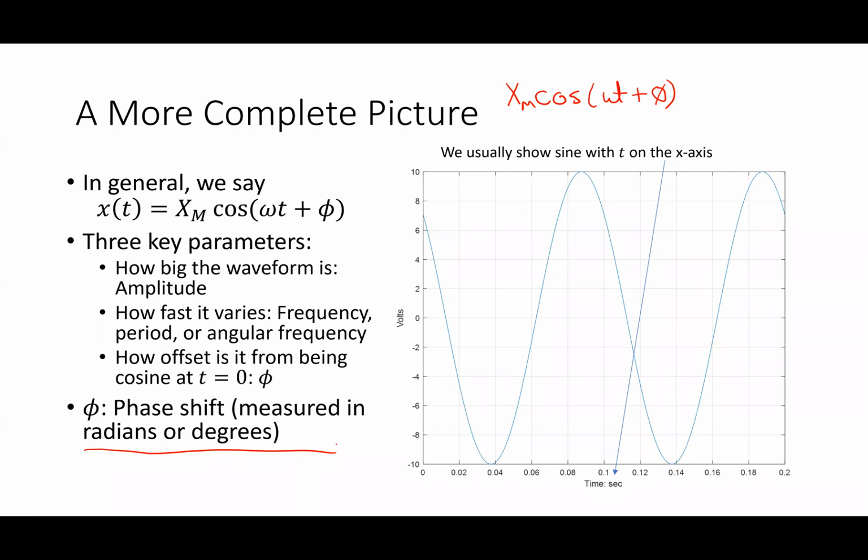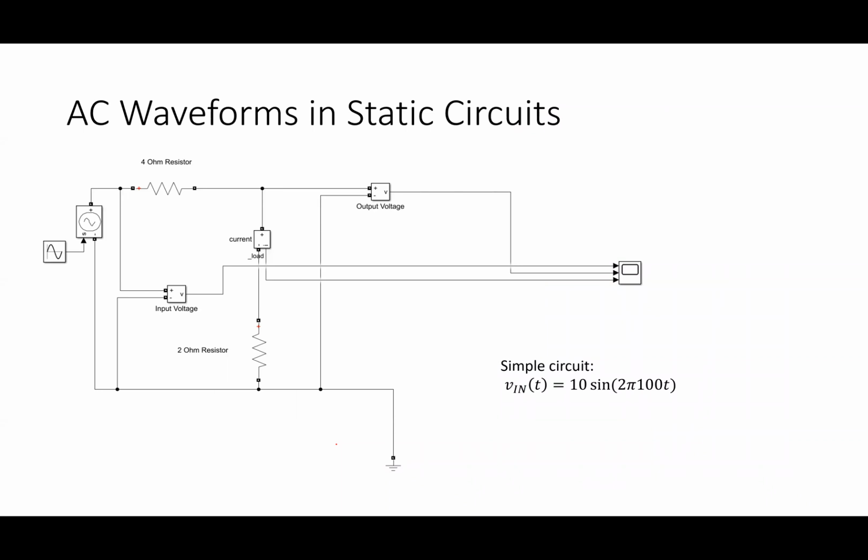All right, so there's a lot to talk about here, but fundamentally, if I had a circuit that had all resistors, right? So here's a case where I basically built a circuit. A little tricky maybe to follow exactly how I've set this up. But what this is, I've got a voltage source and 2 resistors like that. If I told you I had a voltage source like that with here's R1 and here's R2, and I wanted to measure the voltage across this R2, what is that circuit? What would you call that? Voltage divider. It's a voltage divider, right?